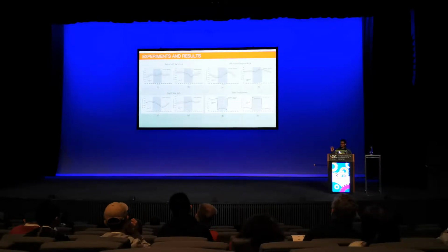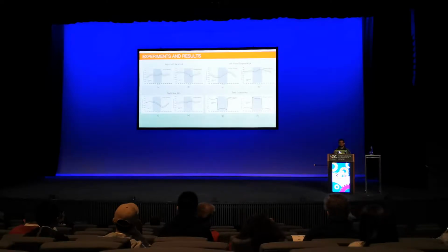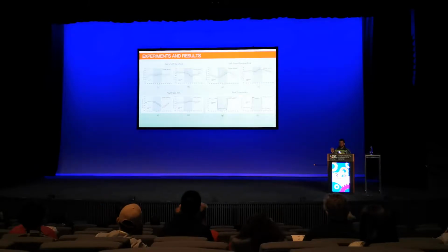So when the robot kicks on the x-axis and has a constant y value, as you will see in front and back kicks, the center of mass is relatively close to 0 on the y-axis. Since all these kick trajectories can be classified with a set of center of mass trajectories, the combination of two center of mass trajectories can explain a unique kick direction. For instance, if the robot would execute a left front diagonal kick, we expect the center of mass to shift towards the positive x-axis, figure F, and positive y-axis, figure E. The same can be said for any kick direction, and this concept was supporting the experiments conducted.